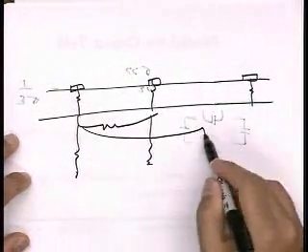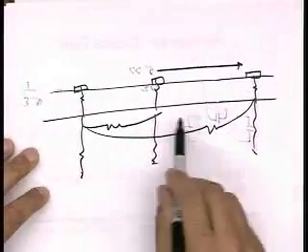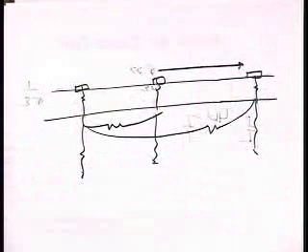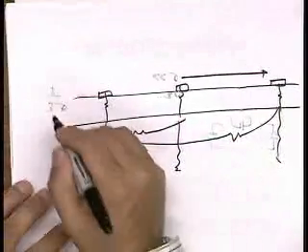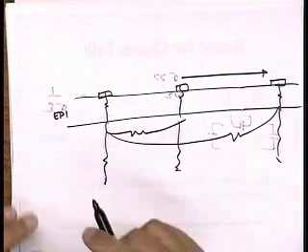So if I move this contact back, how much does the coupling change? In other words, does my crosstalk improve? And so let's say we're talking about an epi substrate. Is it going to help a lot to move back and forth? Okay, Michael, you have an opinion? I don't think so, because you go down to the low ohmic one and then it's short anyway.